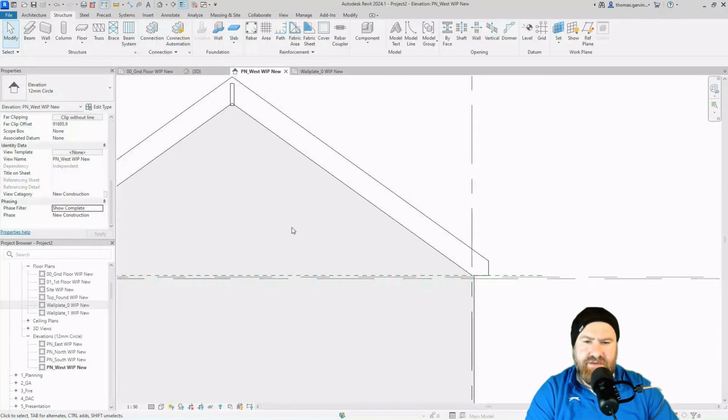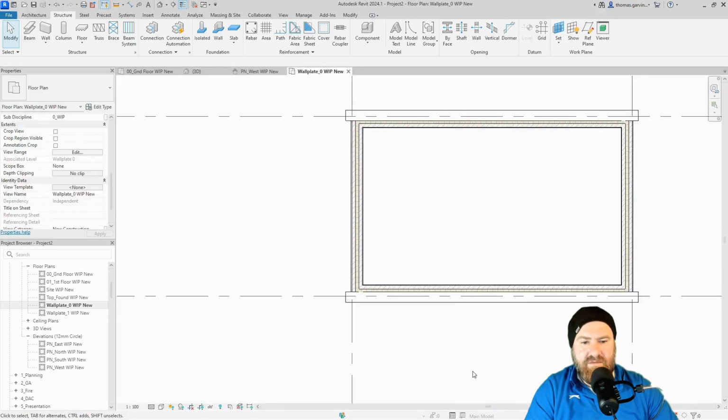I should mention, actually, that just to make things simple, I made everything 150 millimeters. So the structural depth of the rafters is 150. The roof overhang on the roof is 150, and the fascia height is 150. Okay. Now I'm going to go ahead and use 18 mil boards for fascia and soffit, and I'm going to attach the roof structure to them and notch them and so on, and you'll see a bit of that later. But for now, I'm going to go into my wall plate plan, and I'm going to insert a fascia board.